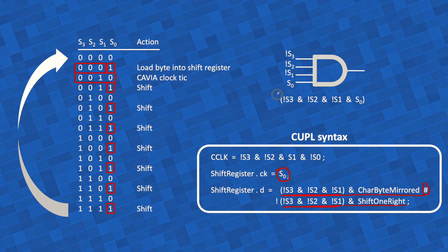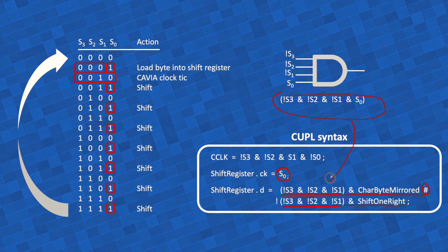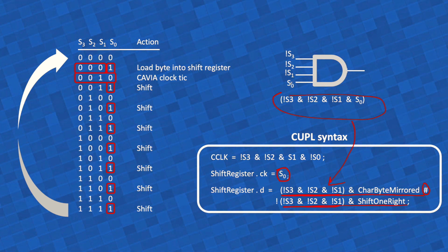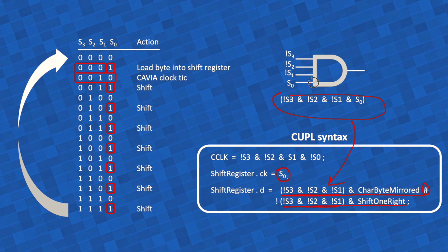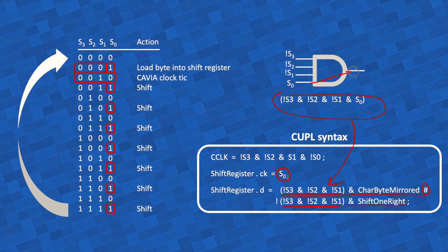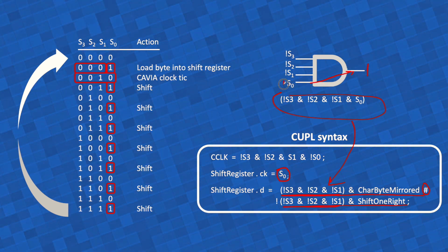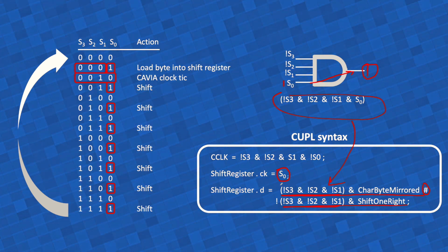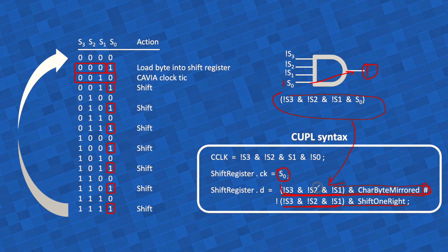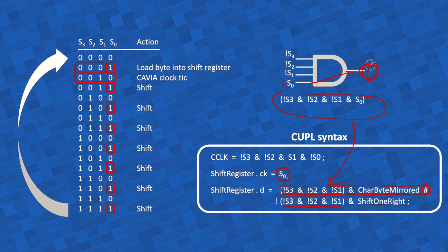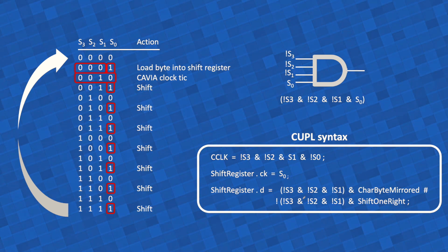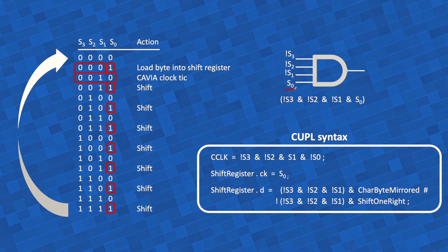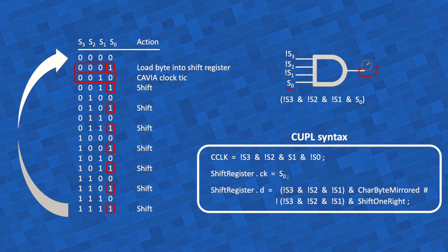Now, if you put this condition there, remember that's the implementation. By the time S0 becomes 1 here, there will still be a gate propagation delay before the output becomes 1 there. By the time this output becomes 1, and then you would do a parallel load instead of a shift, the input has already been latched, because the input will be latched as soon as S0 becomes 1, not as soon as this output is ready.